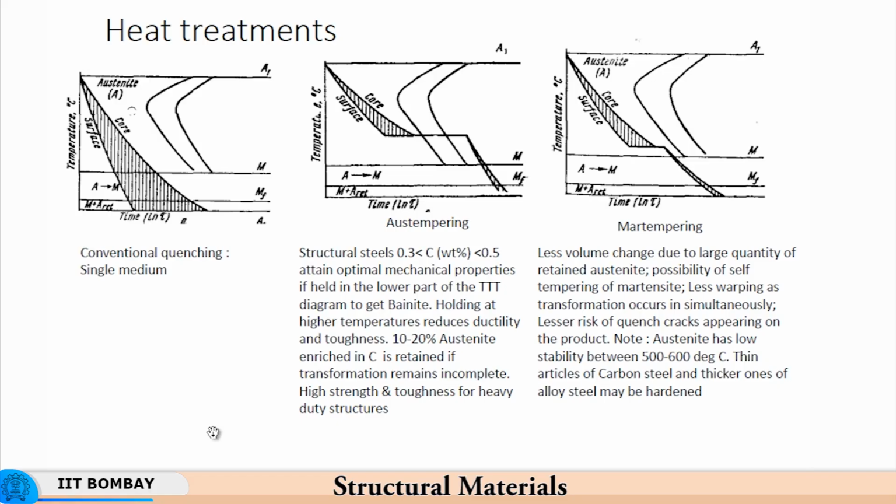So, we have already seen this austempering process, but here we have bainite with 20% of austenite, right. And then if you subject these to cryogenic treatment, the retained austenite will get transformed to martensite again. So, you will be left with no retained austenite at all. Now, one advantage of retained austenite is that it will increase the toughness of the material.